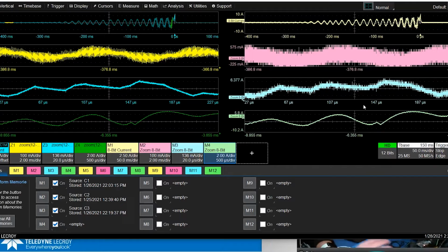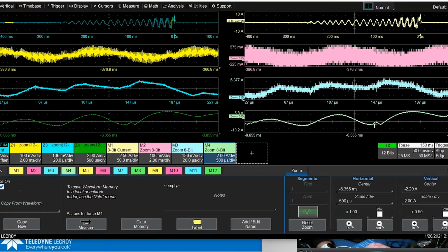I want to compare dynamic range for you. Again, we're trying to find the small details in signals, maybe ripple, maybe this type of signal. We want to see the details, make measurements, and then accuracy was the other point I was making. You can see the noise on an 8-bit is significantly higher. This one is a zoom of the 8-bit. That's looking better than I would have thought, frankly. I would flash back this, but nonetheless, you get the point.